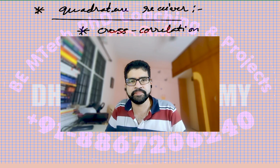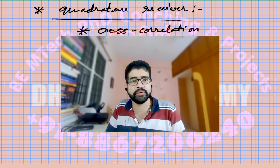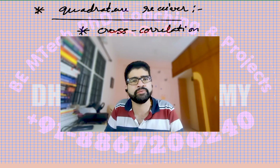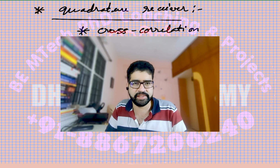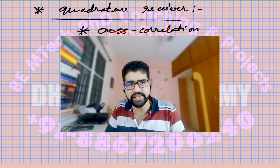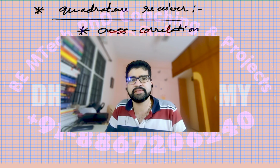This is called autocorrelation. The second is the correlation between two completely different signals, x of t and y of t, where I want to find out the similarities. Since you are performing the correlation between two completely different signals, this falls under cross correlation.